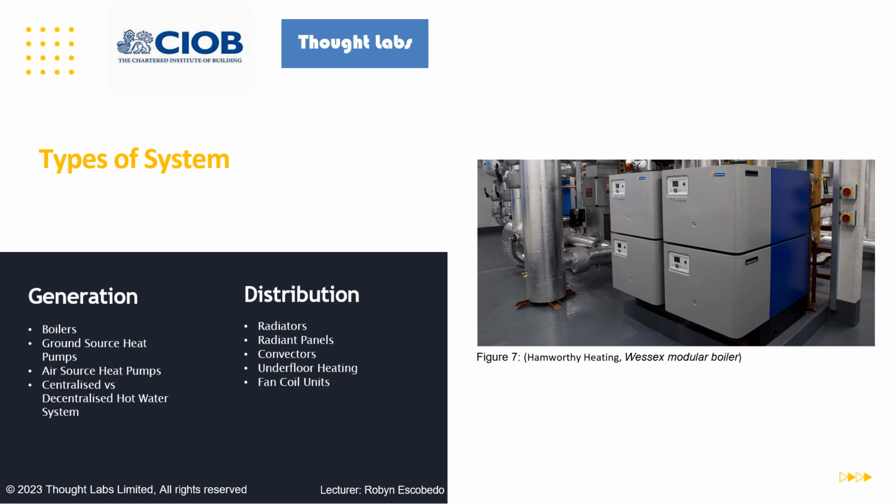Boilers may be modularised, so in the figure in front of you, you can see there are 4 boilers. To consider the implications of this, we shall imagine that this building has a 400 kilowatt heating load. If one boiler was used that had an output of 400 kilowatts, then even at times of low demand, e.g. 60 kilowatts, that 400 kilowatt boiler would be running.